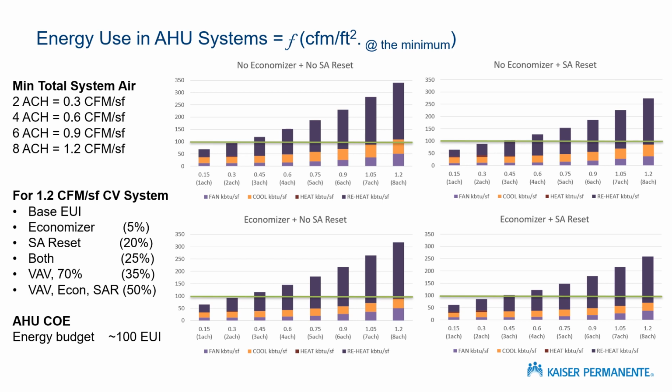So just to talk about neutral condition, I live in California, and so in Southern California here in Long Beach, when it's April and it's 3 o'clock in the morning on April 1st, and the outside air temperature is 69 degrees, right? Which means there's no heating load, there's no cooling load, there's very few people in the building. Any lighting system that can be off is off. Any equipment that can be off is off. Any patient that can be asleep is probably asleep, and we're down to a skeleton crew on the night shift. That's the neutral condition for a hospital.